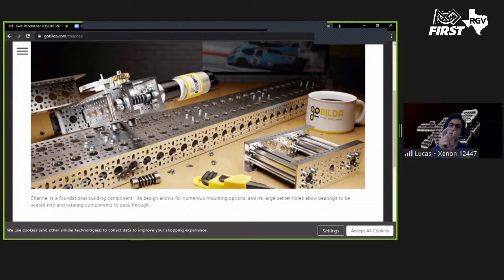What I would do is make one little square with all the holes and use a pattern to repeat it. So what we just covered was a circular pattern. If I was doing that, maybe I would use a circular pattern to CAD out the holes surrounding each large center hole that you can use for bearings. I'd use maybe a circular pattern to make those screw holes. And once I have a certain set block, I'm going to repeat that block all throughout the entire rail, or C channel.